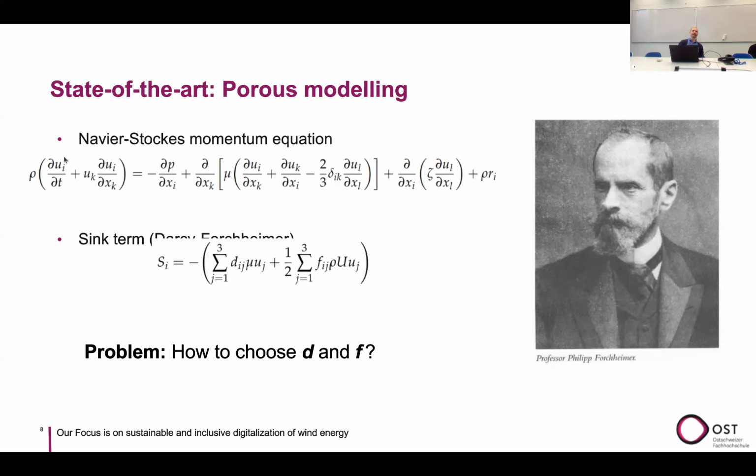Here you have the derivative of a speed, so you basically have something like an acceleration. I'm going to be a bit hand-wavy about it. So this is basically our acceleration, the density is basically like a mass, so ma, and these are all the forces. So we have pressure forces. This huge term is just viscous forces. This is bulk viscosity, so it's another viscous force. So basically the forces that happen inside a fluid. And then the last term is just some other force terms in the fluid that is being modeled. So it can be like buoyancy, gravity, stuff like that.